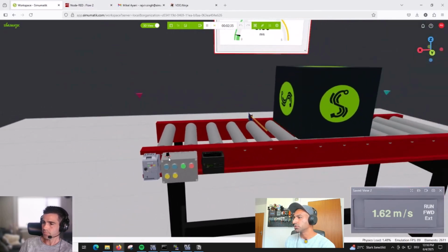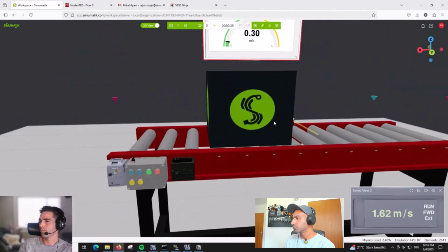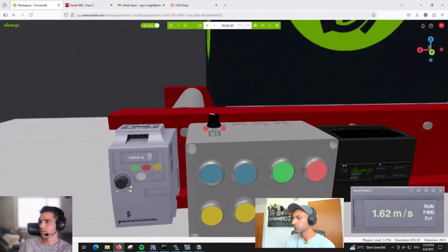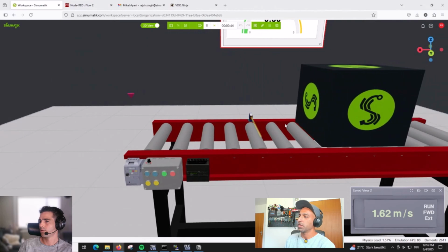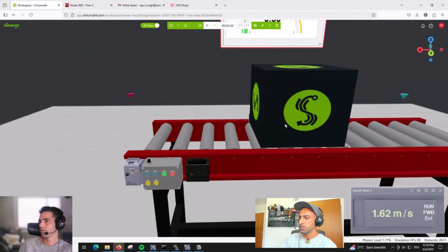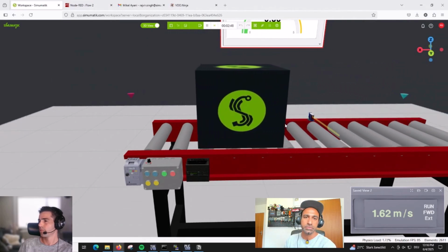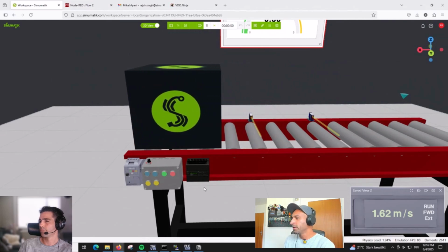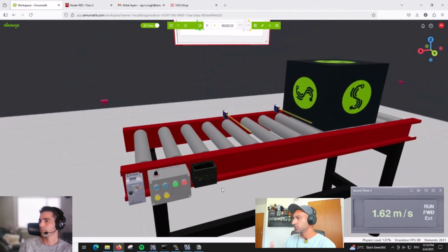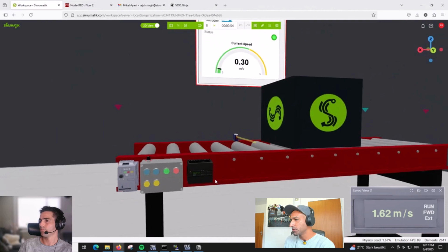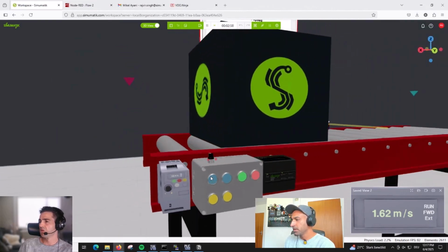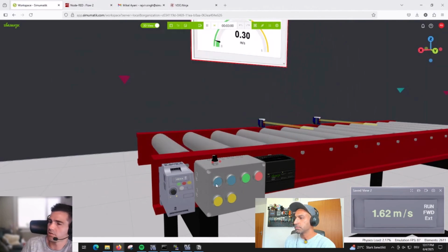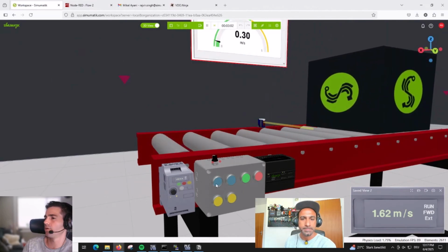We can also imagine connecting the sensor outputs to this VFD external input. The thing which I was doing with the PLC before, I can do directly using the sensor signal, giving it to set point 1 and 2. So this is also possible. Or you can also use a relay to latch the signals, things like that. So it's very flexible to use this VFD with external IOs. For simple applications, I think it covers a lot of possibilities.